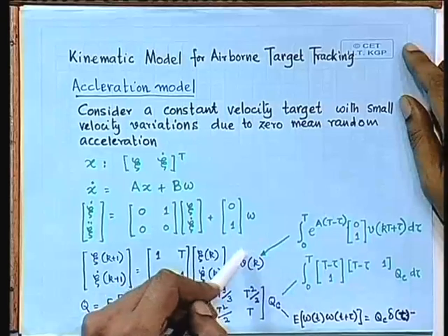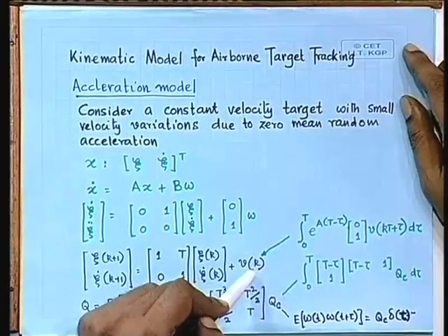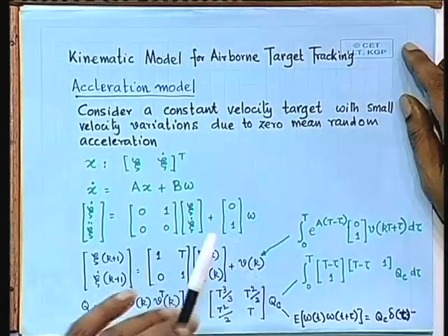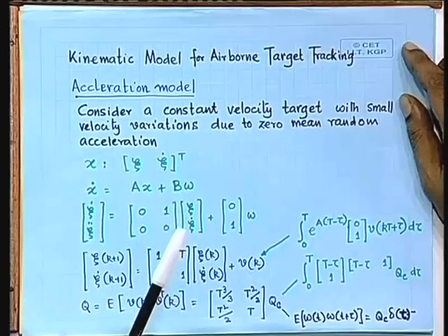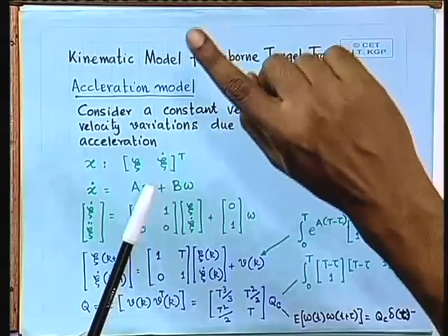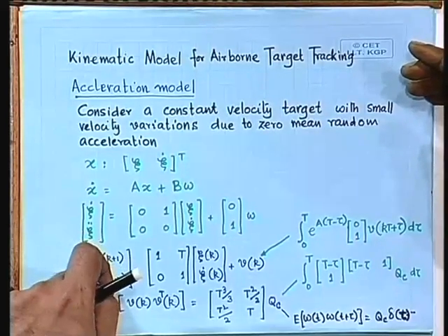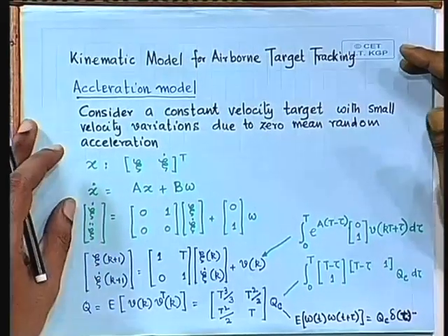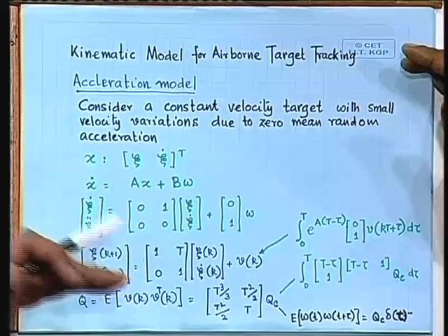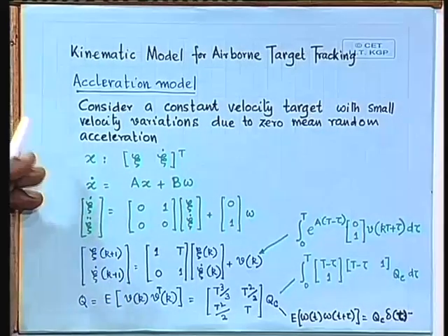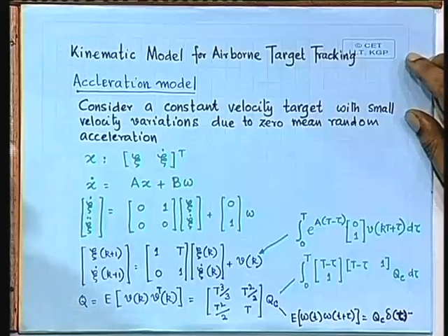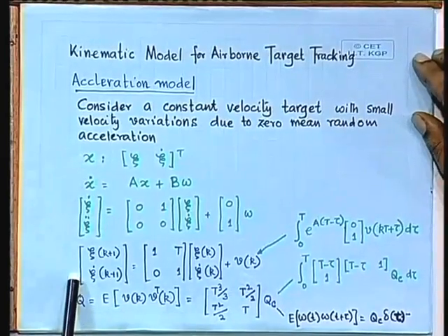That total accumulated effect you are approximating by a constant signal, as if at the kth instant you applied a constant signal Vk which remained constant from k to k plus 1 and produced exactly the same sampled value of this xi dot k plus 1, right. That is how you get it, right. This is what is known as a step invariant approximation of continuous time systems to get a discrete time model. So this is your discrete time model.